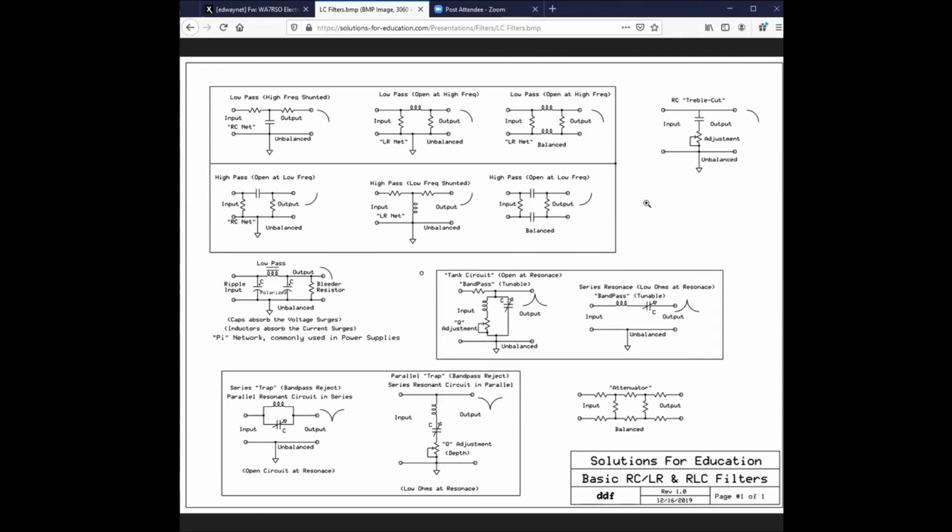Dave, how much inductance is in a straight piece of wire? Oh my, it depends on the frequency too. We used to say that skin effect. Oh, by the way, let's talk about skin effect. That goes into what you're talking about. It's in less than microhenries, but what happens is as current goes through the wire, let's say that we're reciprocating. The current is going in, changing, coming back, back and forth, back and forth. Where is the electromagnetic field the strongest? Well, it's right dead center.